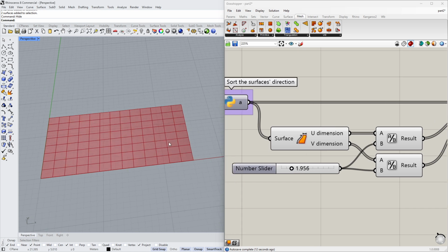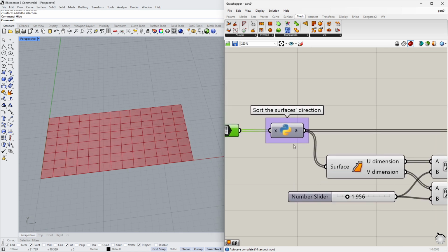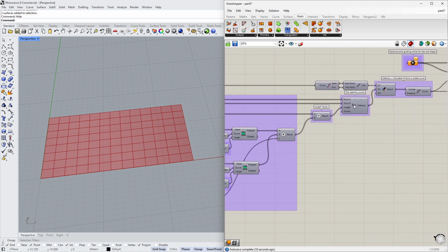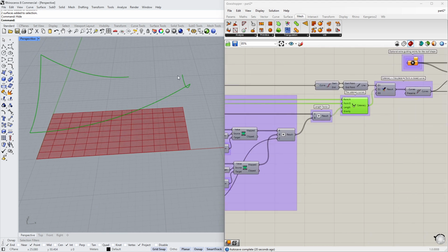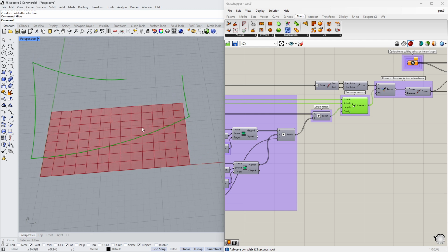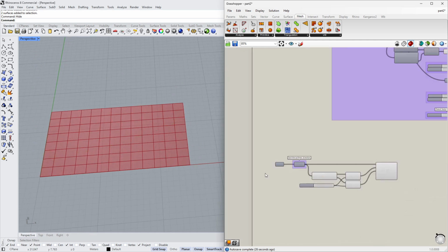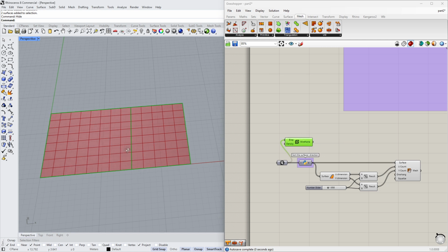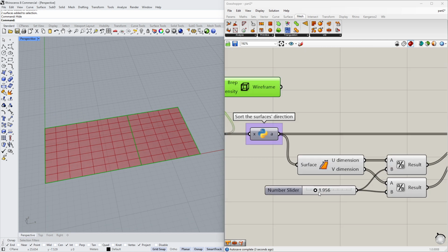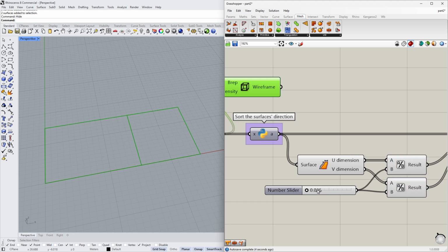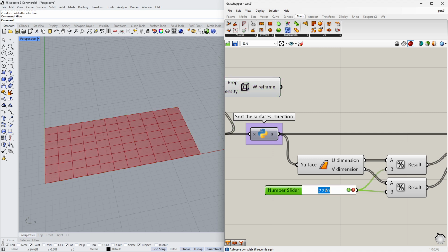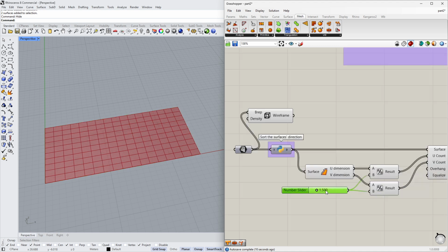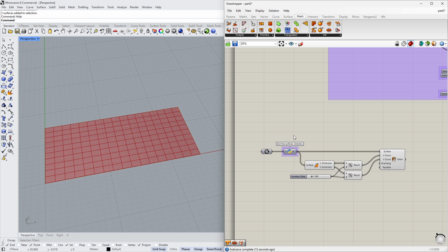And the nice thing is the reason we drew two surfaces, let me show you, is so they would line up exactly where the straight line piece here starts. Right? So let me show the wireframe of my surfaces. Exactly in this line, so no matter how I change the dimensions, you will always have a cutoff here. And that's precisely what I want. Let's set it to 1.5. All right, so this would be the panelization of my roof.